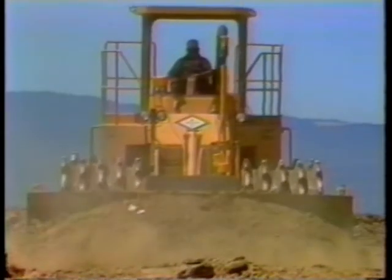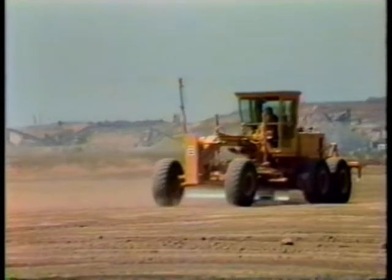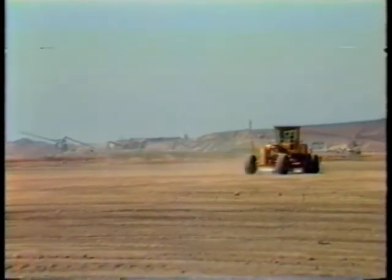Third, all the elements of the beam are parallel and in phase with each other, so there's no interference between them. That's one of the reasons the beam does not spread out like a searchlight beam and can be used as a very accurate reference beam, in this case to make a field perfectly level.